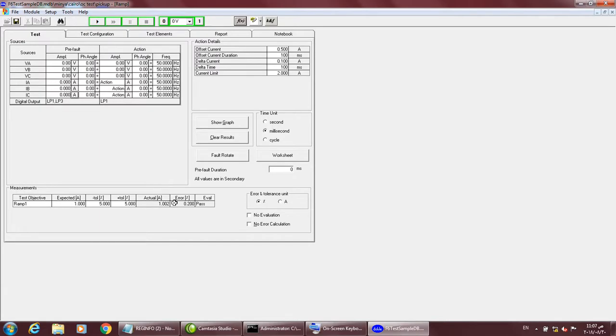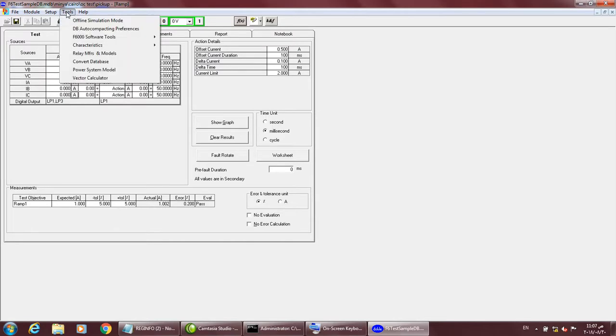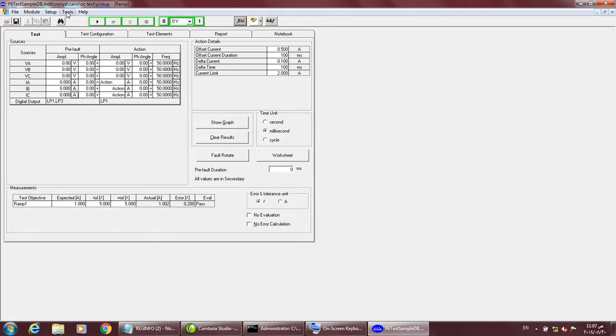Timing is coming here. So now if I run this test, it will give a random timing. I have selected 1, so it is near this one. When you actually test, the same will be in actual mode, at what exact current. So this is the pickup test. Now we want the drop test as well.